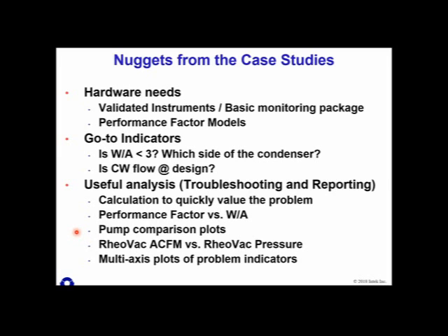You'll always know what CFM you should be measuring at any given time. So making those CFM versus pressure plots, that's this one, making a pump comparison plot. So if you have 2 or 3 vacuum pumps, or vacuum pumps and steam jet ejectors, you can swap them in and out and do your comparisons that way. That's another useful analysis technique right there.